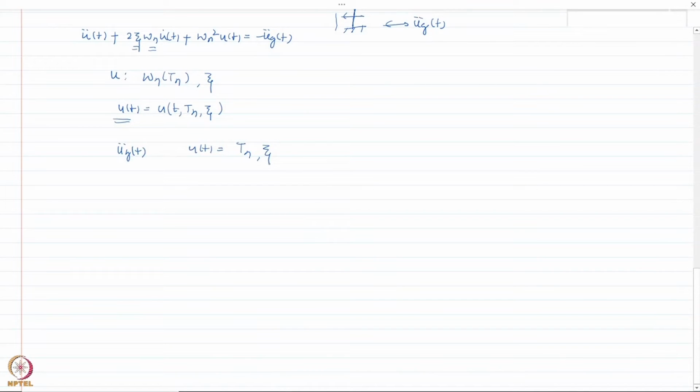For this case, remember, it does not matter whether the system is heavy or lighter, or whether it is flexible or rigid. Two different systems with different masses and stiffness would have similar displacement if the ratios are such that they give you the same value of the time period Tn. So that you have to keep in mind.